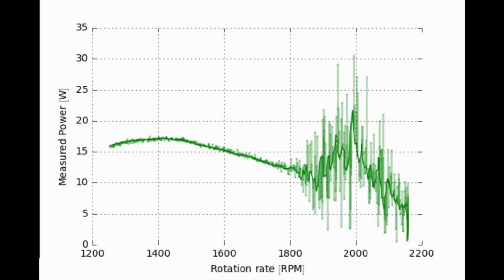The TSR is not what we designed for, but this is due to the interpretation of the data from the graphs. As can be seen from the graph, the max power generated is found in a fluctuating regime of the graph at a high angular velocity. This is what causes such a large divergence from the design TSR and was not factored into our original calculations.